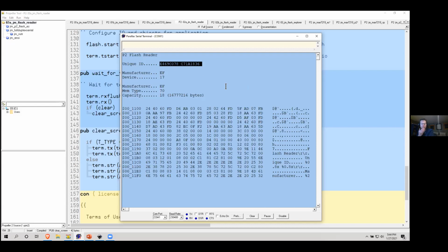And could you comment again on the amount of space in the flash that you can read and write to? Well, technically you can read anything and you can write to anything. For the P2, I'm saying, because again I'm overly cautious, if you want to do experiments with writing, and that one program does that, keep that above the 1 megabyte point. Now, I know people are thinking, but wait, John, there's only 0.5 megabyte in the P2. Well, the P2 architecture is designed to accommodate 1 megabyte. So after the P2 is dominating the world and Chip says, okay, I'm going to make a P3, we just habitually want to stay out of that space. Just keep it above 1 megabyte. It's easy to think about.